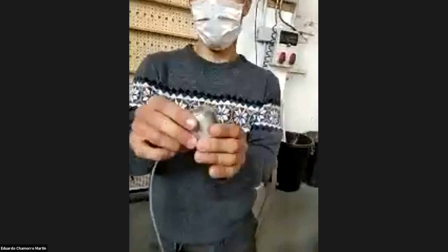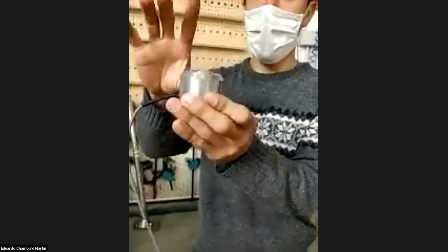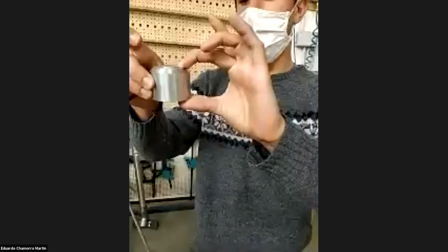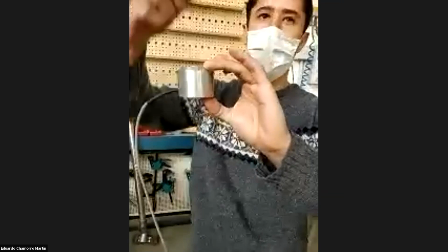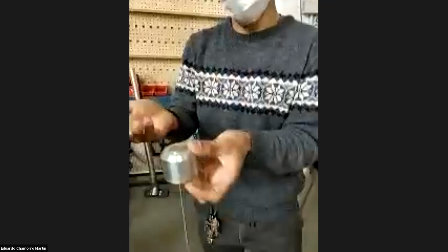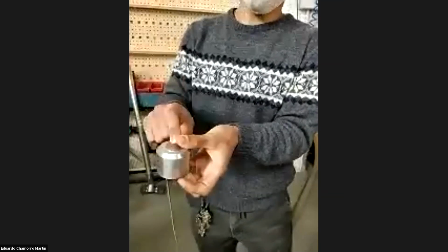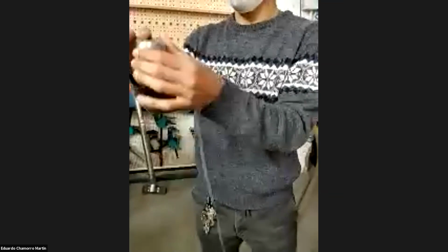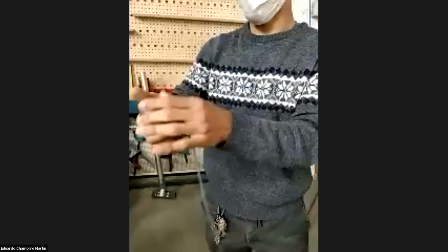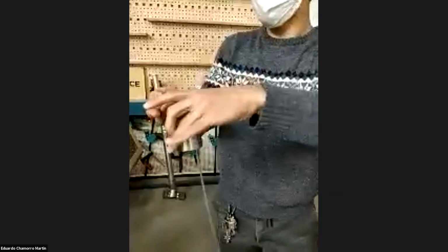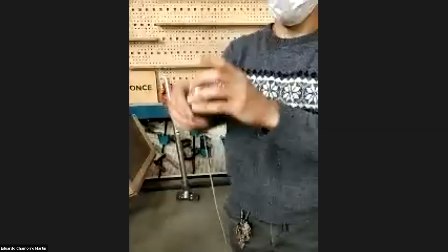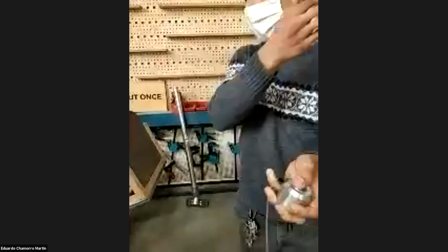If you don't know, especially in CNC machines, the size of the stock, you need to put something that you know the height of, so that your end mill touches, and that way it goes through. And that can be done either with this type of thing or like the previous one in software, which has an electric plate and conductance between the end mill to an electric plate that you put on top, closing the circuit, touching like two cables, which is the same as this, but a bit more attached.